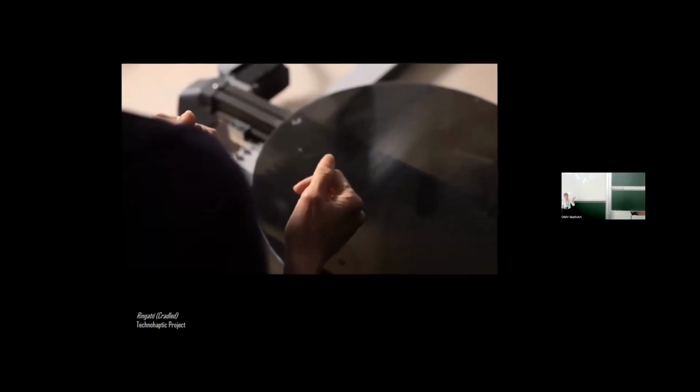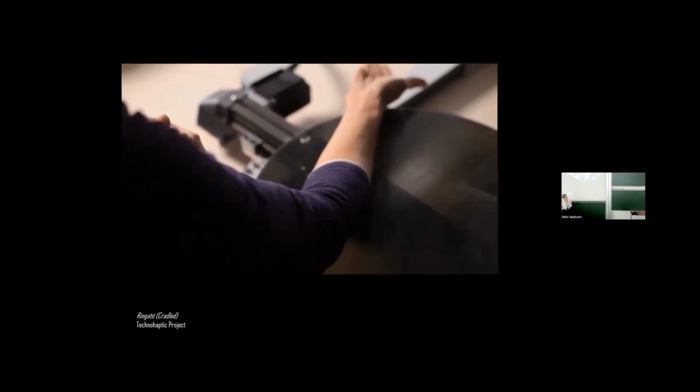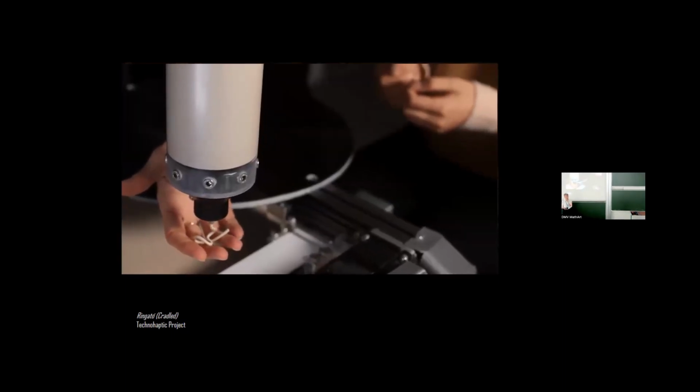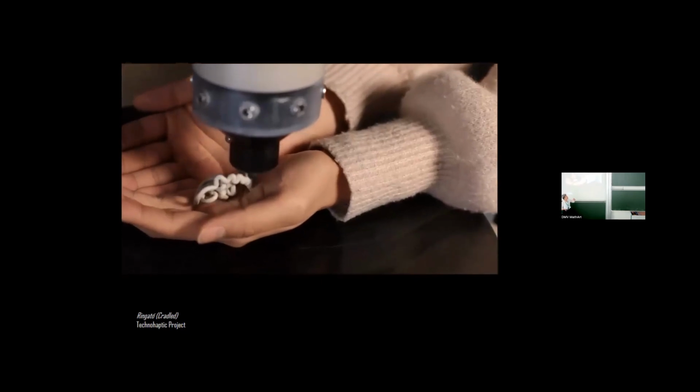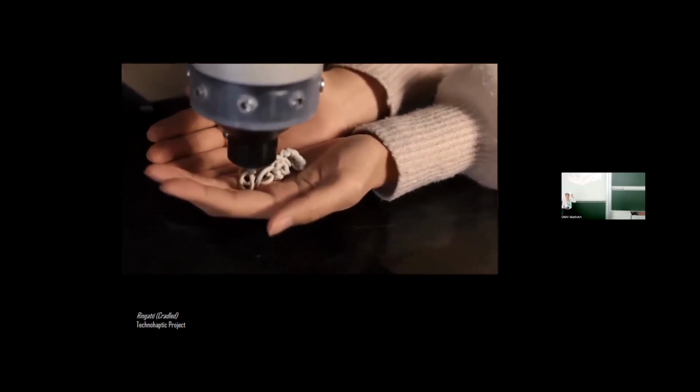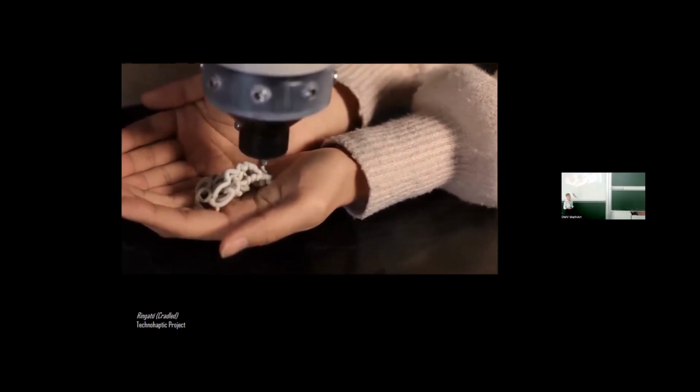You will see a 3D printer here. And by the way, this is a project where the human hand is directly engaging with the 3D printer. Normally with 3D printing, you would be printing onto a platform. The platform is very stationary. In the case of my 3D printer, which is a PotterBot 7, the platform is moving, so the XY axes are moving constantly, and that's how they find the coordinates. And the nozzle itself, the whole extrusion unit, is only rising on the Z-axis.